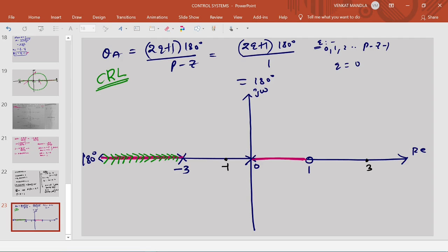And this one, zero to pole. Here the gain k is -infinity at 0. Here also it is 0, k equal to -infinity. At a pole, k equal to 0. That's it. This is the complementary root locus plot for the second question. That's it.